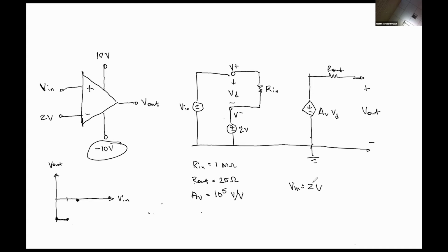I think we may have touched on this in our other classes. It's a sinusoid, isn't it? No. So let's look at Vn is 1.99 volts. So what's VD in this case? -0.01. Okay. And if I multiply that by my voltage gain, what's my output voltage?